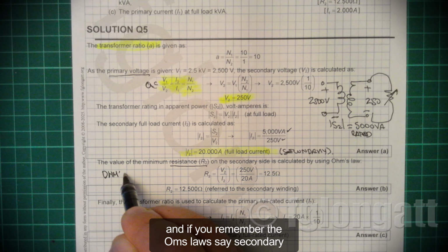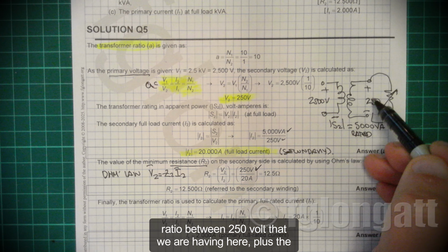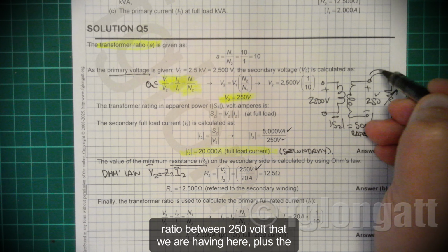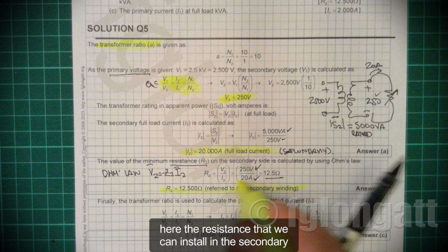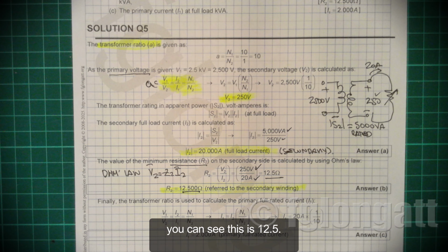So we can define the resistance as the ratio between 250 volts and the current of 20 amps. We obtain the resistance that we can install in the secondary winding to mimic the full load of this transformer, and this is 12.5 ohms.